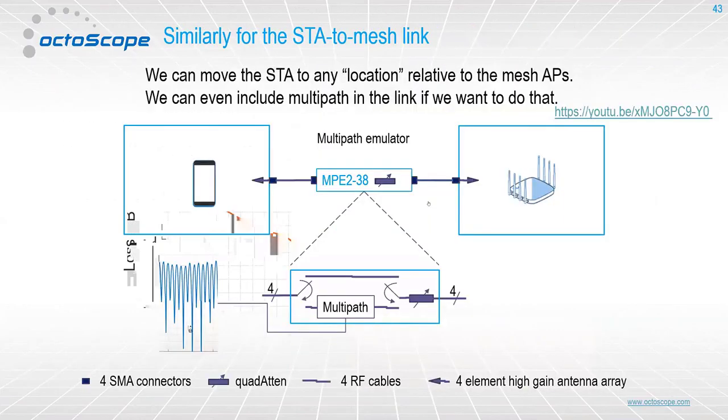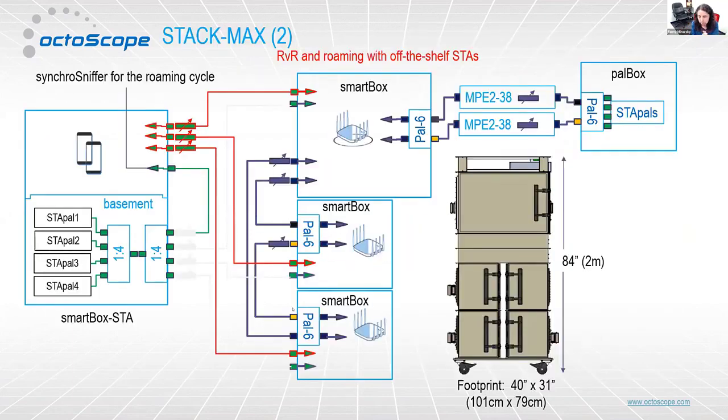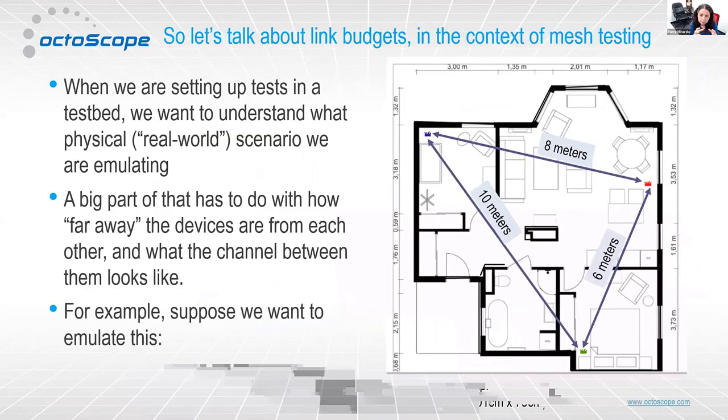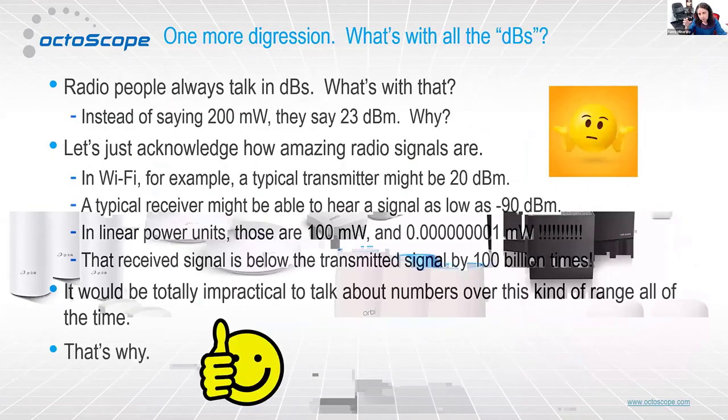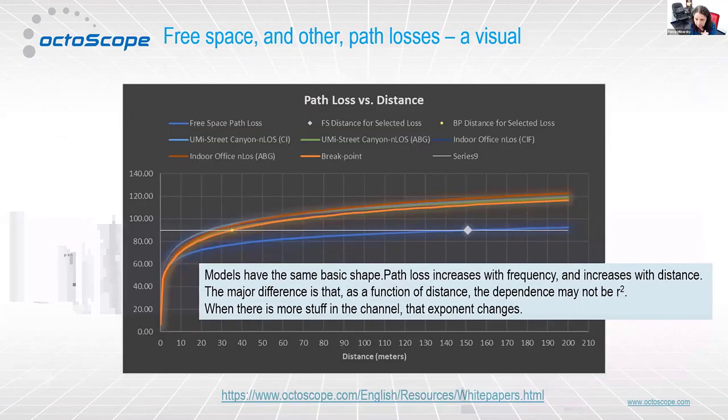Thanks. If you asked about outdoor environments, essentially you have customers using the Octobox for CBRS and LTE. Those are outdoor networks. So it all comes down to, like Lee was showing, modeling the path losses. Outdoors, you have fewer walls, and you would have different multipath, but in urban environments, for example, you could have buildings and different multipath models. It translates into path loss.